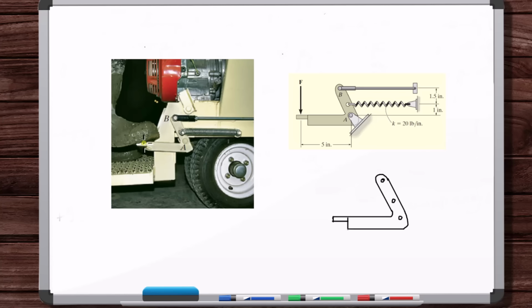Okay, so we see there's contact with the foot here. There's contact with something at this pin point. There's contact here and there's contact here. So there you go. Those are the only forces on this link, forces of significant magnitude. Okay, but the next thing to think about is these contact points. The force at these contact points is going to be distributed over the contact area. Is the size of that contact area significant compared to the size of the link? Here we can say the answer to that is no. So in other words, we're going to just put point forces at these points.